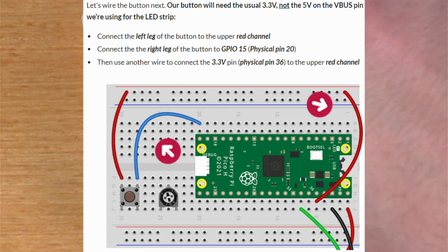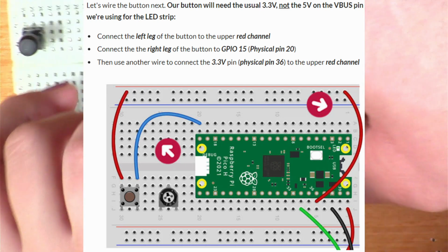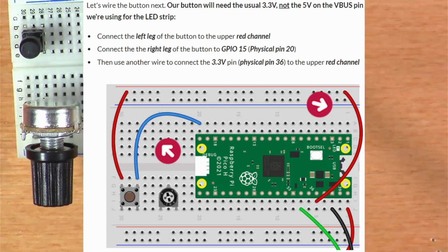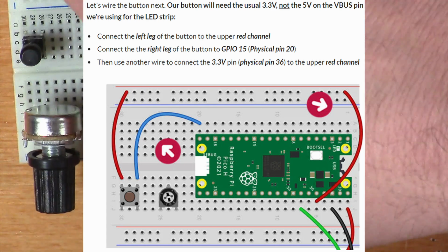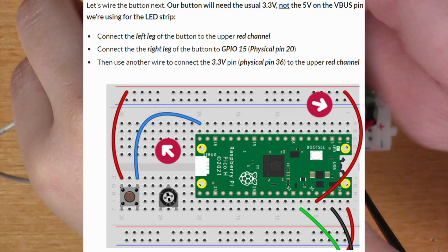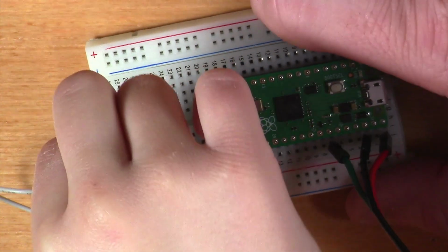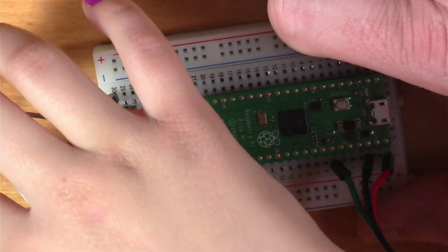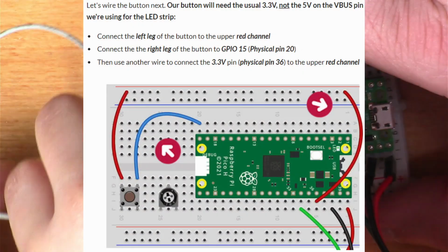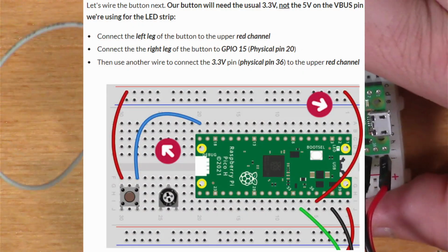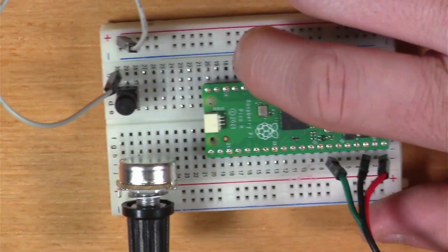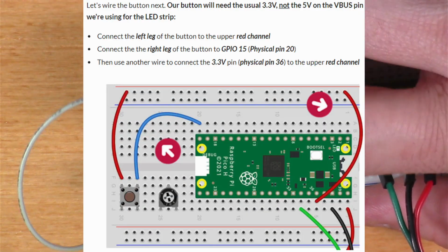If you guys remember from the other project where we used that, the little volume control kind of thing. Okay. Now, so that's a little different. So let's wire this up as it says. All right. So take a jumper. So go from that left, like 30 or whatever it is on the breadboard there, above the switch on the other side. Go in that 30 hole right there. We're putting it in a different place, right? So see, that's what we're doing. See the switch right here? The switch is here, and it goes up to there. See, like the drawing. Put a 28, and then take it over to 20.